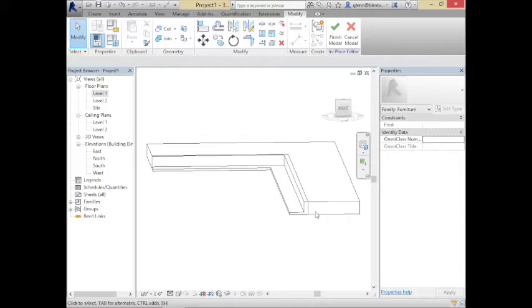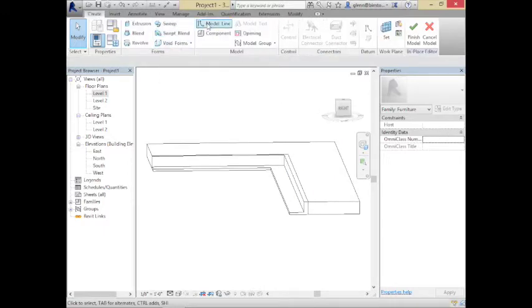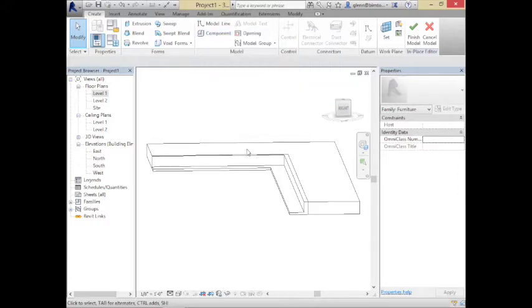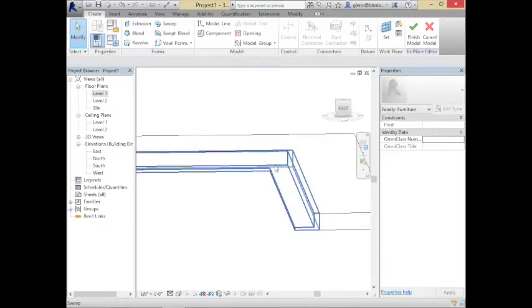And you can use it for other types of objects. Let's say we're trying to model this object. First you create a regular extrusion with a rectangle, give it a thickness, and then you would create a sweep along this path, and do the same process. It could be anything you want it to be, really. Okay, does anybody have any questions about that? I know I might have gone a bit fast because of time. No? Okay. So let's try one more form and then hand it over to Glenn.